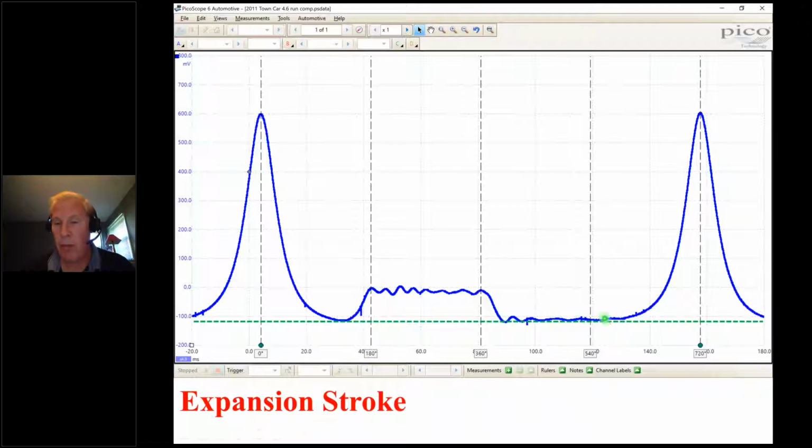This is where the pressure starts, and this is where it ends. And again, there's symmetry in the valve train as well, and I'll talk more about that. So as you do your analysis, as you study this, as you talk about this with your students, if you decide to do that, you always want to compare that point to that point. The vast majority of gas engines, they will be very, very close. There will be some engines that there may be a 1 or 2 inch mercury difference between them, but most engines will be pretty close.